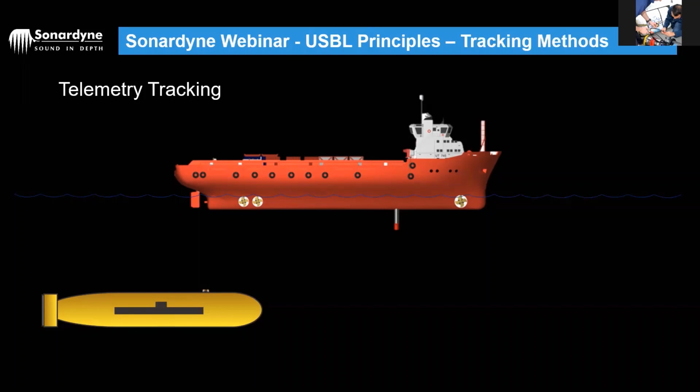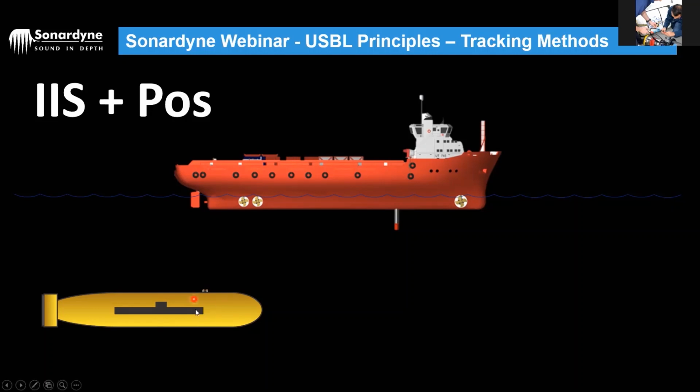And what happens when we're tracking an AUV in telemetry tracking or robotics mode is the interrogation we send to the AUV contains a time-stamped position data from the previous calculation. So if the previous interrogation, we would have got a position fix for the AUV. So that information and the time that we got it is included in the next interrogation to the beacon. This enables the AUV to go, well, I think I'm here now, but if I was there 2 minutes ago, then that makes sense. Then I'm on track and that's all working. All right. So that's basically a key part of what our robotics pack does. The other things the robotics pack enables, and it's basically a common response back again. So you get the response back in the normal mode.